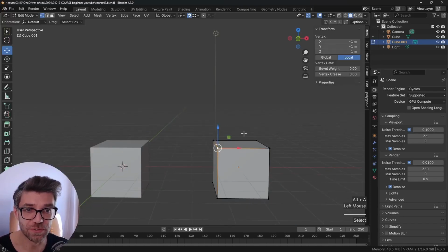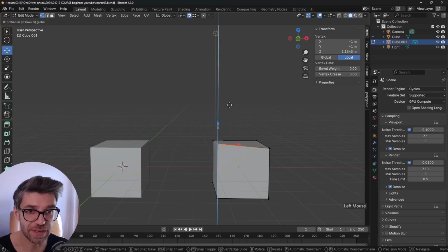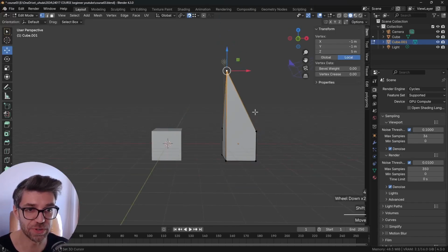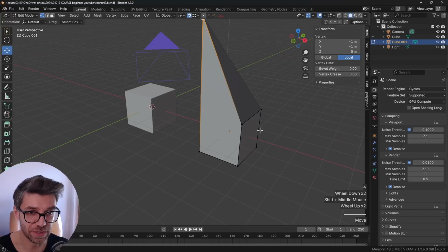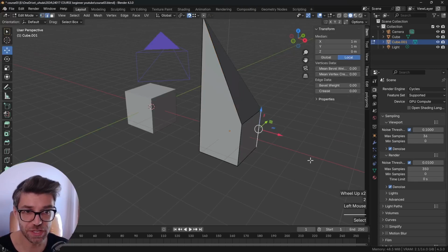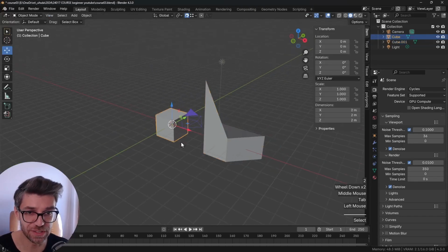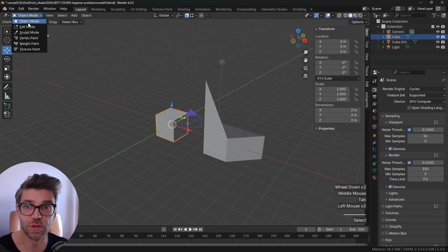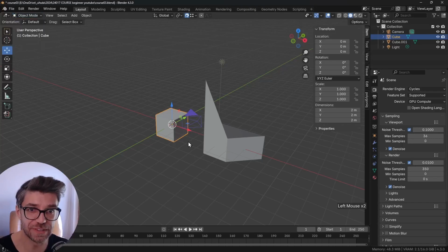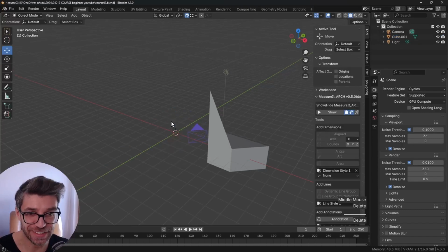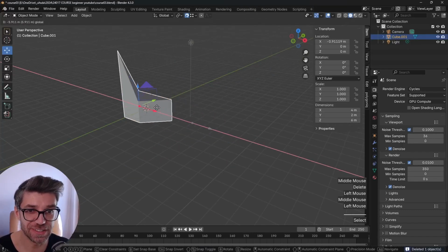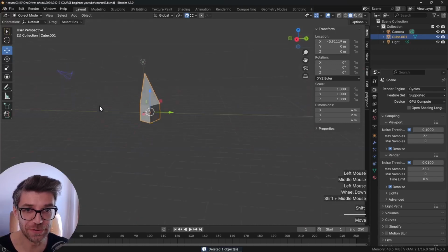Cool. So edit mode, vertices. So we can move things around if we press the move. And again, with this gizmo active, I can press a number and press 4, and we got something happening here. Let's hold now this edge by pressing 2 and move this too. And now we got something else happening here. Let's erase this. I'm going to swap between object and edit mode with the tab key. That's the most important hotkey that you need to learn. And let's get rid of it. And now we've got this little fella here, which is rather interesting.